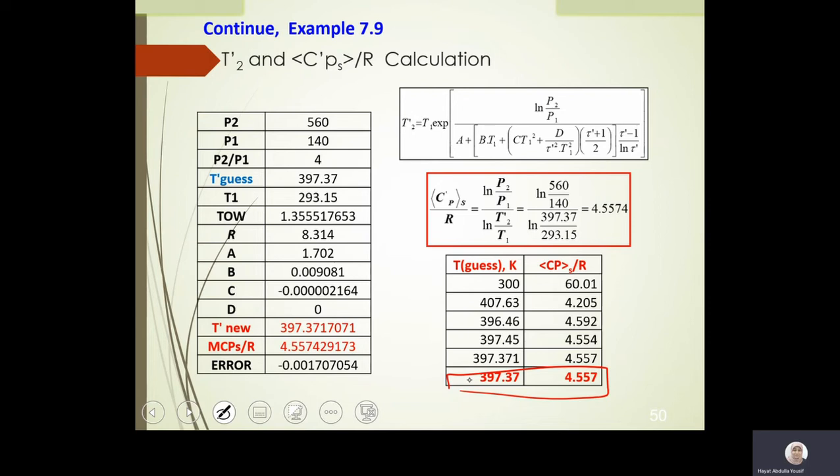So you can clearly see that the actual temperature is 428.65. If I compare it to the T2 dash, which we calculated before, it was 300 something. So I can see that there is a difference, and my temperature has been corrected because of using the efficiency equation. So that's basically how to solve if it is an ideal gas, compared to solving using the steam table, which we solved previously. Of course, that's the end of this question.